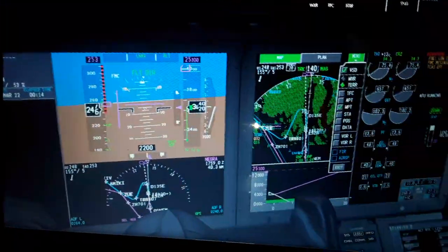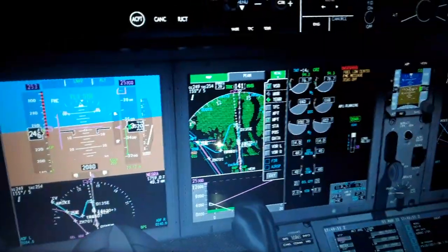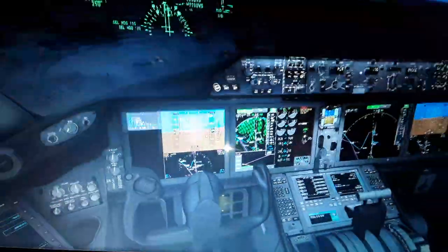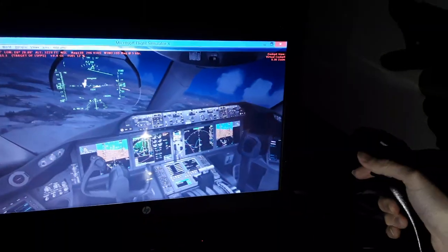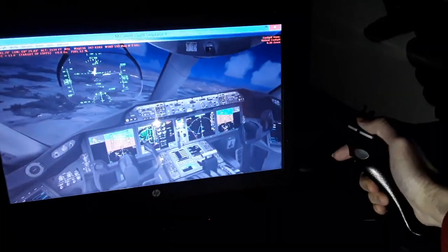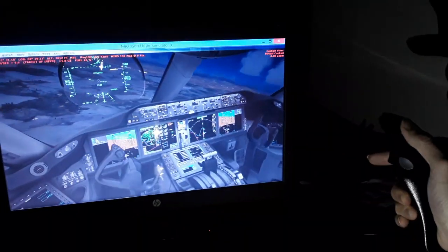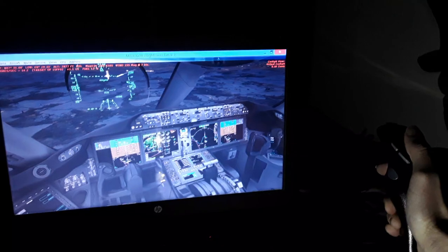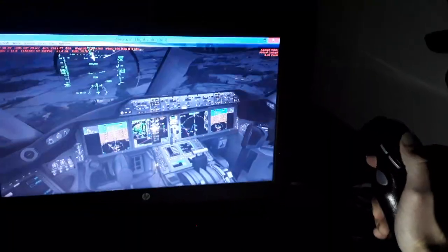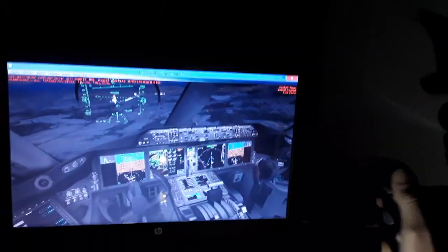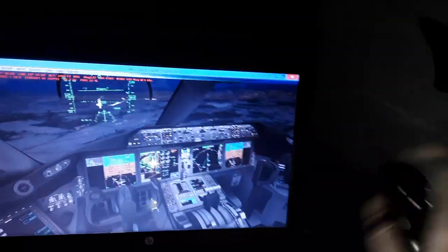You can see also the LSZH localizer here. We have the intercept, the localizer, the glide slope, and also the terrain around you and below you. Here's the information. So we need to align. We have some side wind here, align with the runway. Here's some flight controls, some left rudders, some right now, to make proper alignment before touchdown. I'm gonna use also full flaps maybe.